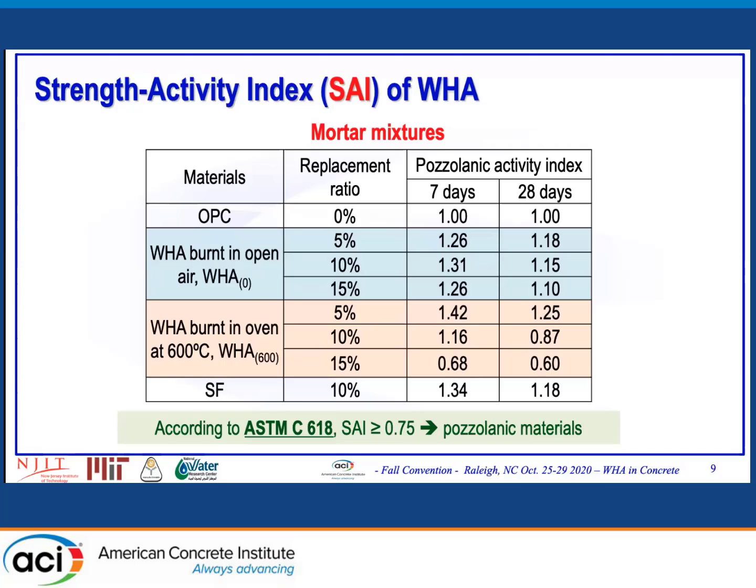So to test any material to see if it is a pozzolanic or a filler, we have to run a strength activity index test according to ASTM C618.